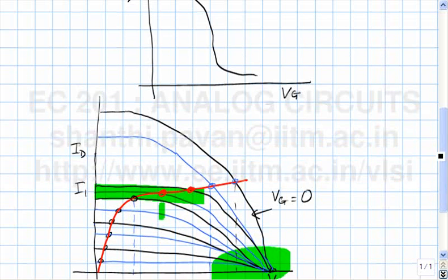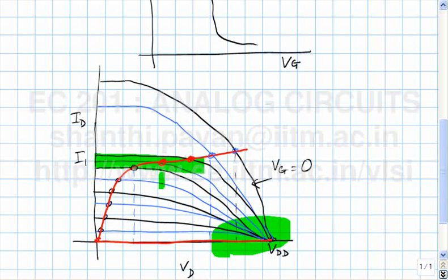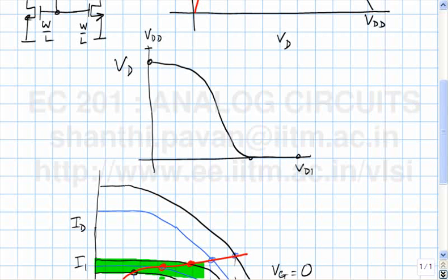If the PMOS current is 0, that will correspond to I being 0. That will intersect the NMOS characteristic at 0. So the output voltage will be 0. This is VDD. This is Vg on the x-axis. This is VDD. And what is this voltage? VDD minus mod VTP. Oh, VTP. Okay, for the purpose of this class, I just assume that VTP is positive. So this is the region in which the gain is very, very high.